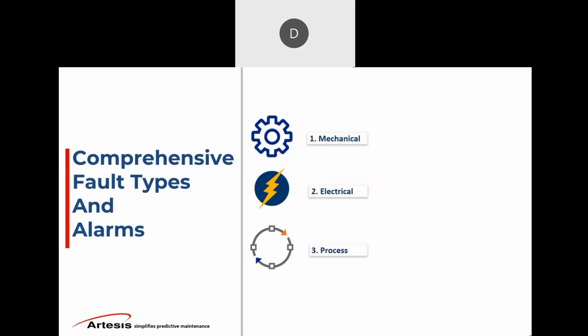This is another unique thing, I think, to what we do: the process-related faults. So it could be leaking valves, it could be plugged filters, it could be cavitation in a pump, all done with one system, and irregular airflow, maybe in a compressor. You can't list everything that we can find there because there are so many different driven equipment that a three-phase AC motor is driving. So it'll learn those particular processes and then be able to flag all kinds of different process-related faults.